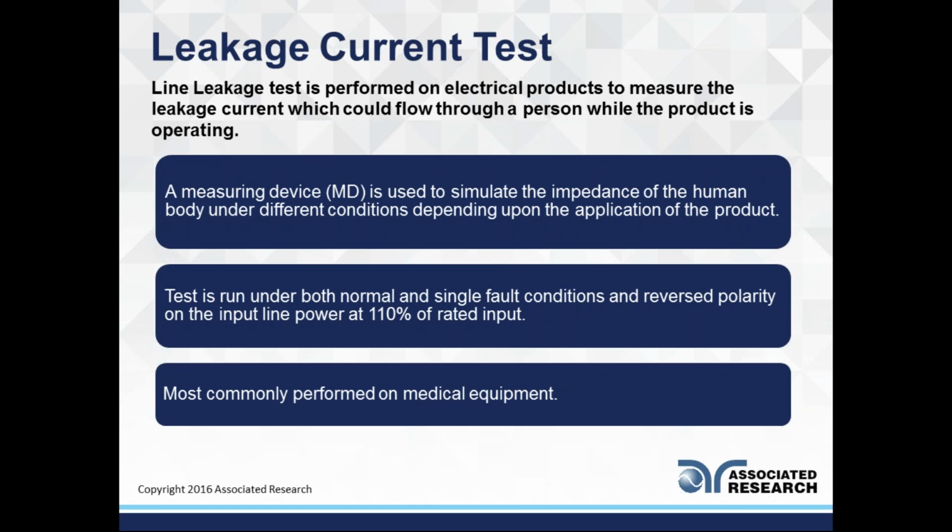Now your leakage current test, this is where we have the most questions, and to be honest, it's really tough to be an expert on leakage current tests because there are so many different types of standards, and they're performed in such different ways. But when it comes to medical devices and other types of electronic devices, we've become pretty educated on it. Always feel free to reach out to our apps group if you're uncertain you're properly testing your parameters and your fault conditions, which we'll get into further.